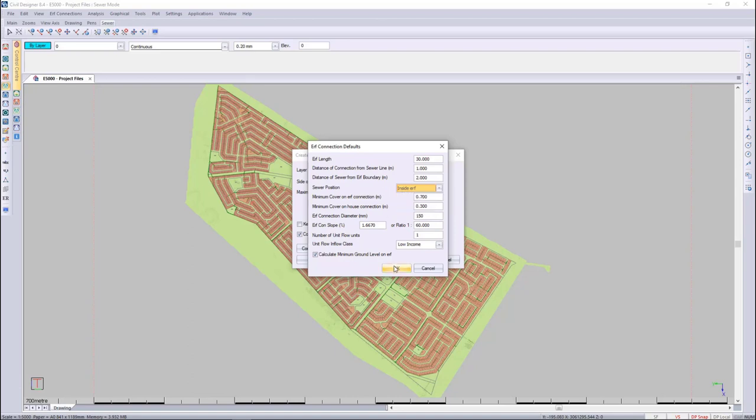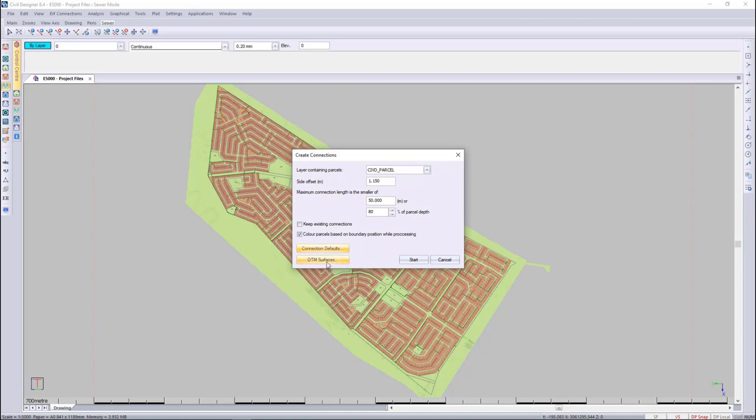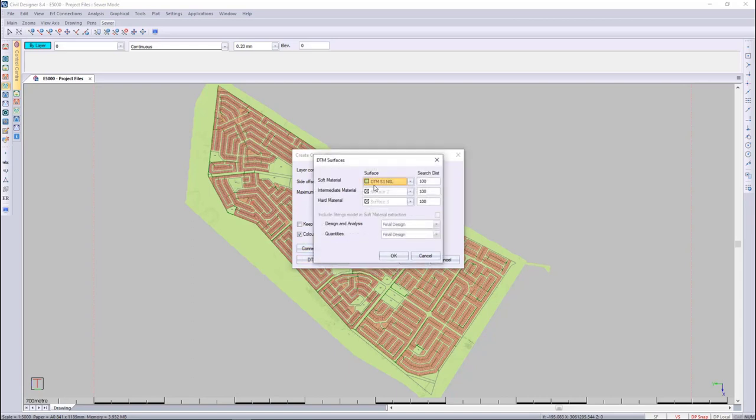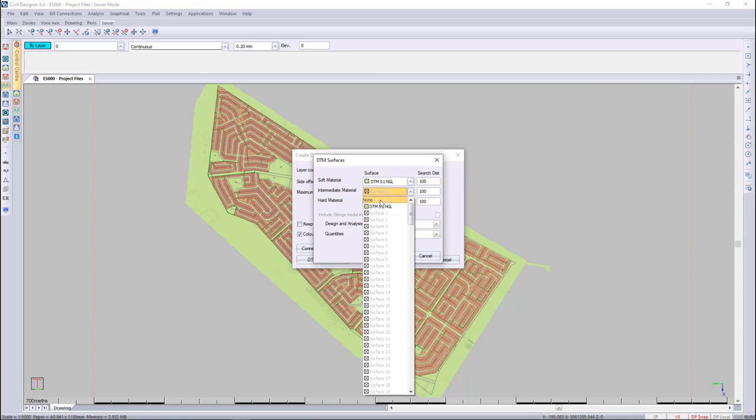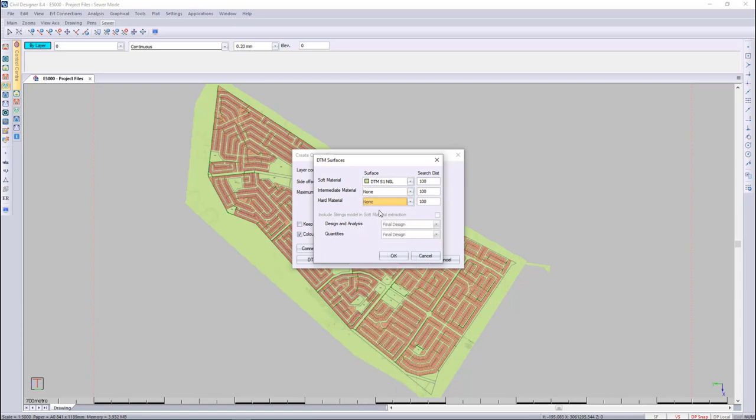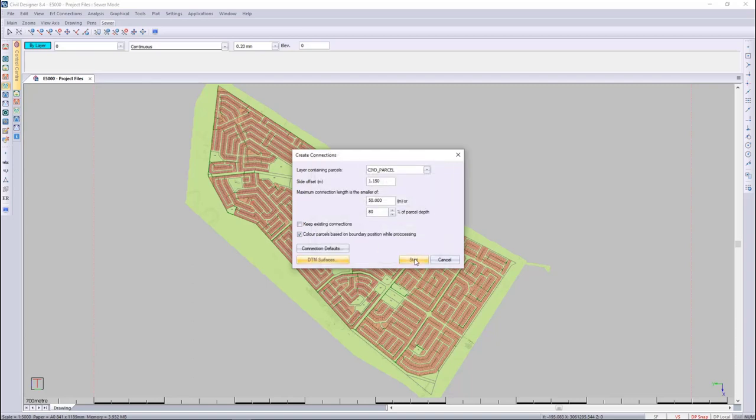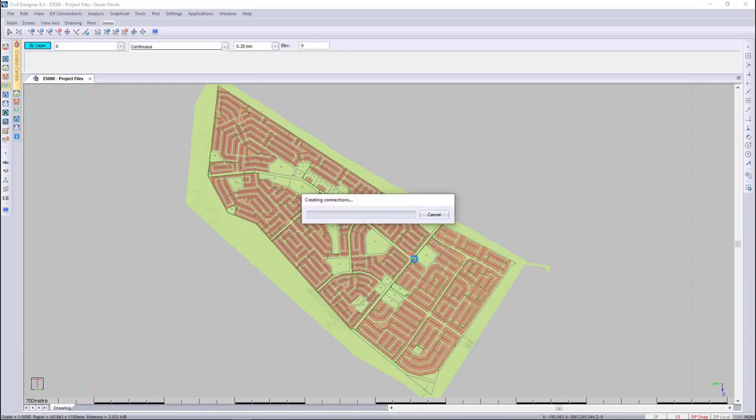The sewer house connections have always been used to obtain the invert level of the house connection, run at a 1 in X slope. Plumbing, for instance, would be 1 in 60, and obtain the invert level at the main sewer pipe, whether that be on a mid-block or in the road. Then you would generate flow contributions to your network. So if it was a new design, you would be using those flow contributions to size your network. If it was an existing design, you would be using those flow contributions to check where there are capacity issues within your network.